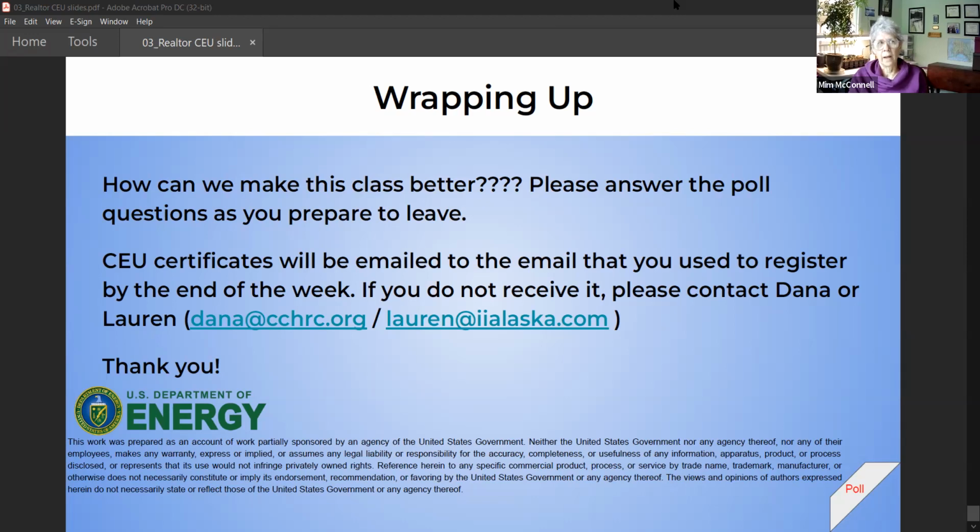Could I just add one more thing? A friend of mine was having problems with her heat pump, and she had a repair guy come and look at it. He said, it looks like you've never cleaned these filters. And she said, well, nobody told me that I needed to. So when it was installed, even, she had not been instructed to clean them. As a realtor, whenever I'm dealing with someone that has a heat pump, or they're looking at buying a house with a heat pump, I make sure to educate them about that very point, because it really does affect the efficiency of the heat pump if it's all blocked. You're just not going to get as much heat out of it.